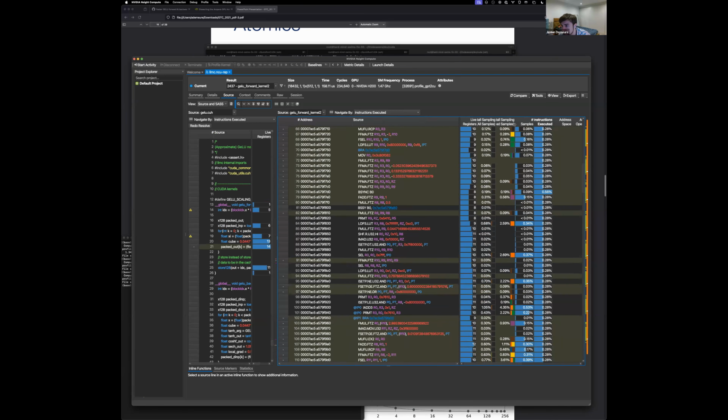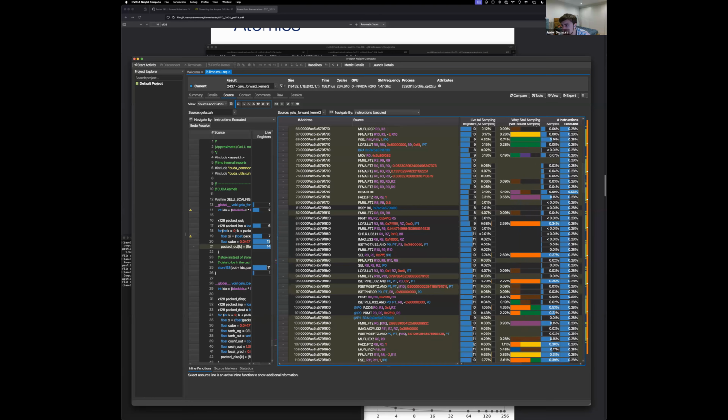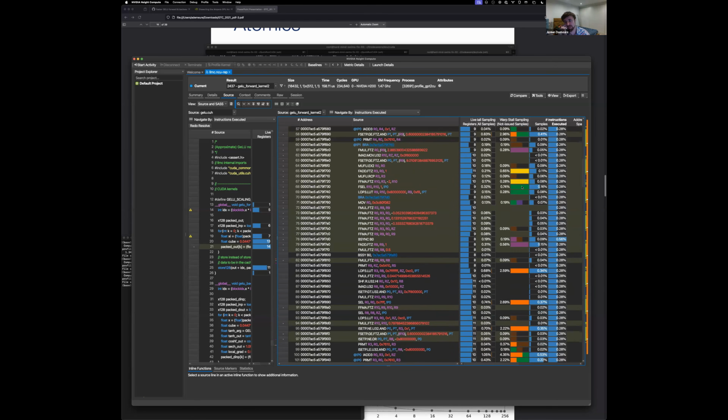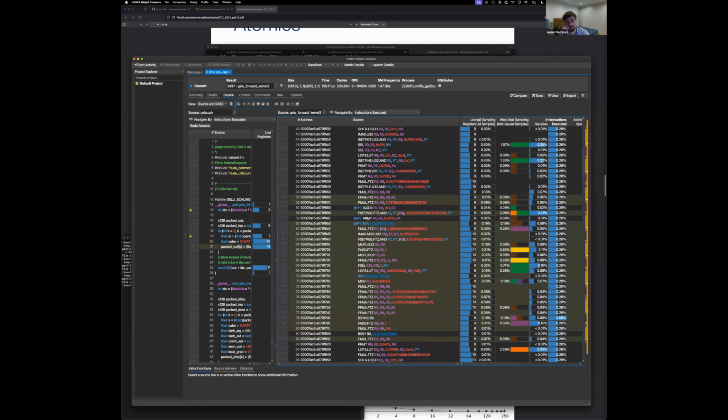I don't think it makes that much difference. No, I see what you mean. It's the case where there was something to execute on that cycle anyway, so it didn't matter that we had a stall from this warp. Yes, exactly. Right, these seem not actually bad warp stalls. If we have enough parallelism, we don't really care. So I decided not to comment so far, but I think this one I must comment now.